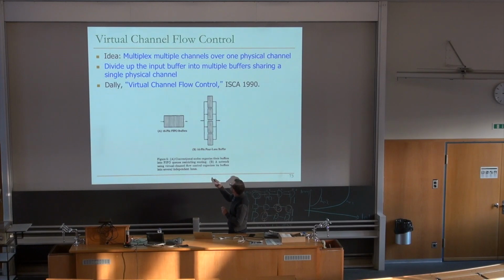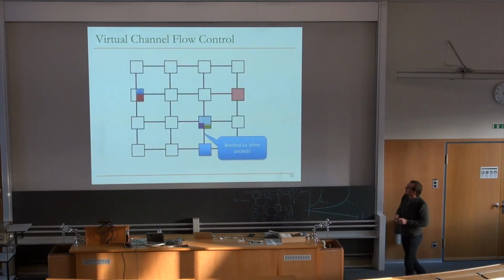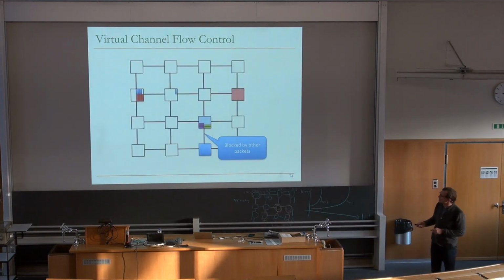Okay, yeah, you can choose only this. Now you can choose only 4 of those. If you actually had complete out-of-order scheduling, you could choose any 16, right? But that's expensive. Okay, so basically virtual channel flow control enables you to have 2 smaller queues.